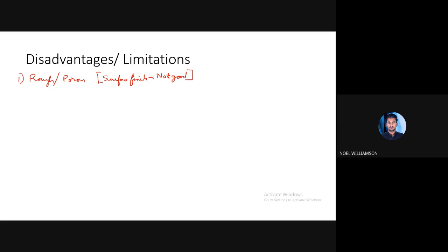Next, regarding the shrink rate. Shrink rate means, as we have seen after casting, once it is cooled the material will shrink. Likewise, here also we are creating layer by layer by the application of heat produced by the laser. Not melting, but still we are sintering the material or the metallic powder to obtain the desired shape. After cooling, there will be a shrinkage.